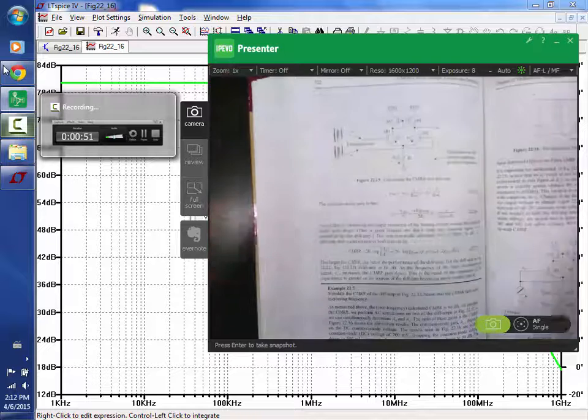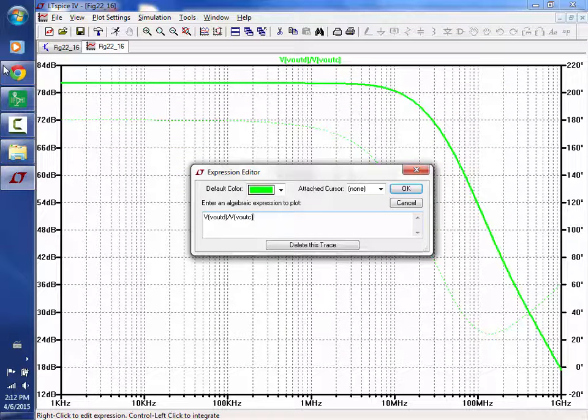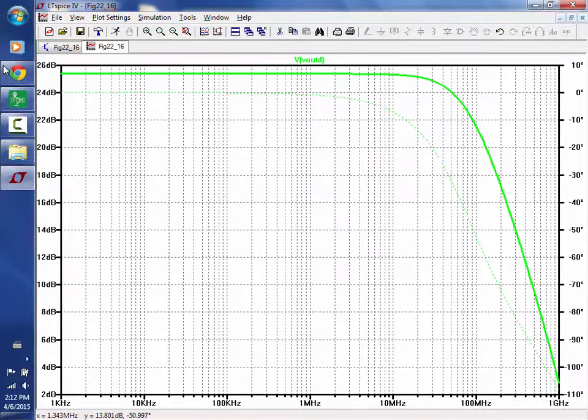You want a high common mode rejection ratio. Okay. So just to show you, there's the gain by itself. It's not that high. Why is the gain only 25 point whatever dB? It's a simple single stage diff amp. That's why we need two stages to have an op amp, because remember, an ideal op amp has infinite open loop gain, so we get the higher gain by cascading.